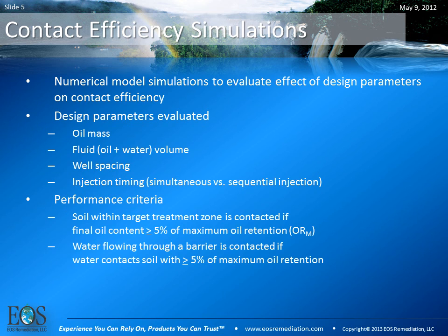But before I get into the nuts and bolts of this model, I thought I'd bring up some of the preliminary work that was done by Bob Borden's group at NC State, where they were doing numerical model simulations to evaluate the effect of significant design parameters for emulsified oil treatment systems. Those design parameters evaluated include the oil mass, the fluid volume, and that includes both your oil plus your chase water, and your well spacing, which is an important parameter.